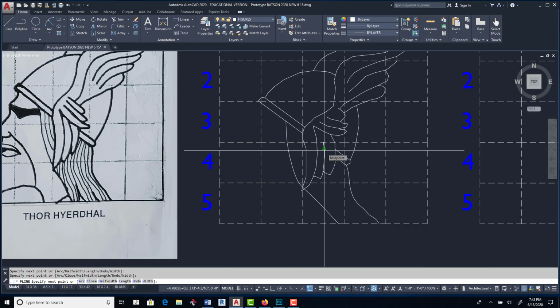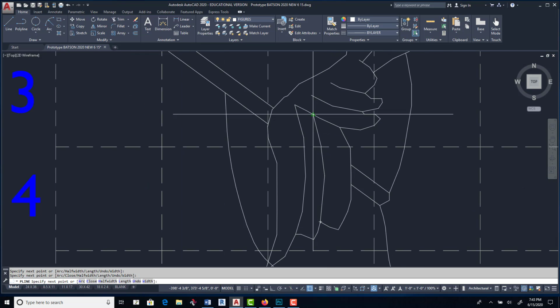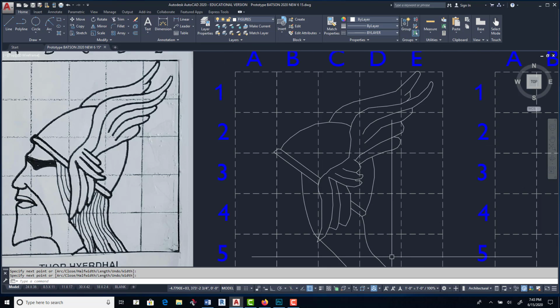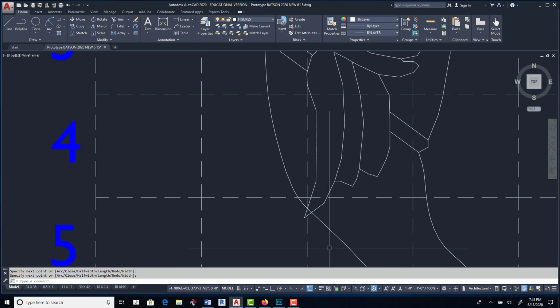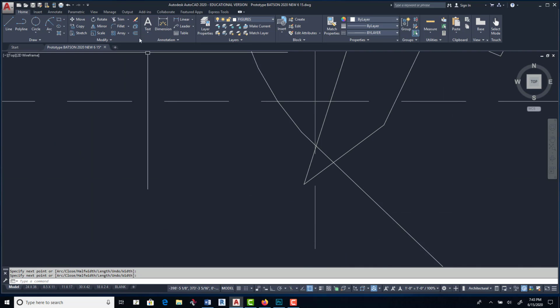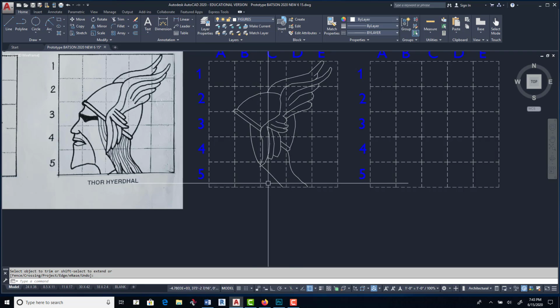Does it go all the way to there? No, it goes up and it goes here. Or you can type in nearest. There you go. Now you got to get rid of that little piece there, remember? So remember our trim command, trim, left select, cutting edge, left select. And now that's a polyline, it's a whole line, so you don't have to select both of them, just select one. Right click, enter, left select. There you go. Now remember our offset command, there's our offset.